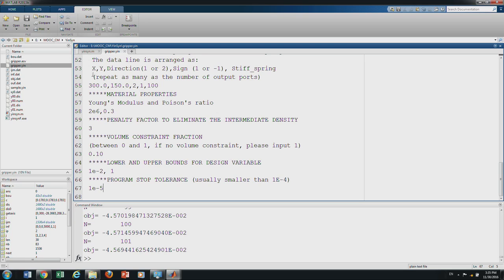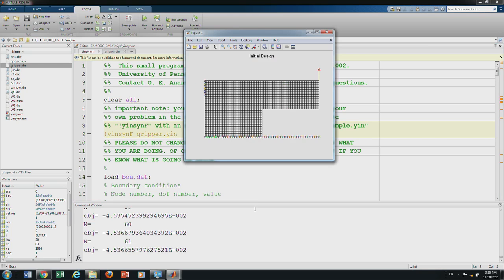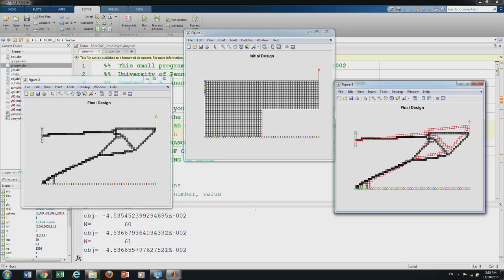Okay. This is what we have, let us save this and run the program again. It is running real time in MATLAB, meaning that if we do it in C or Fortran directly, it would be much faster. Of course, it is running a Fortran program here on this platform. You can see the iteration numbers are just going. If you make it very fine tuned, with a lot more elements, then it will be a little slower, because you have to do finite element analysis at each iteration. Now, it is done and it got a solution. See, it just moved.